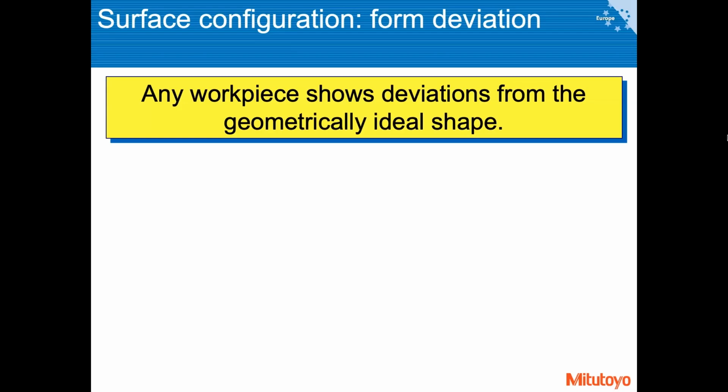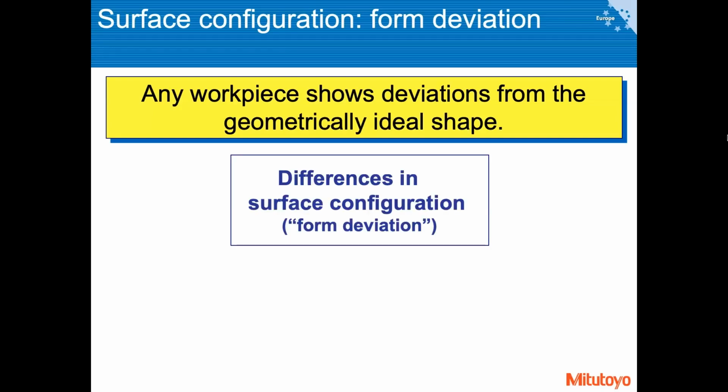So if you are just cutting some firewood, it does not matter if it is plus minus 2 or 5 centimeters, as long as you can put it inside your fireplace. Or if you are preparing artificial human teeth, then you have a very limited space in your mouth in order to put it in. So your tolerances must be way lower, and the same is also true for surface roughness.